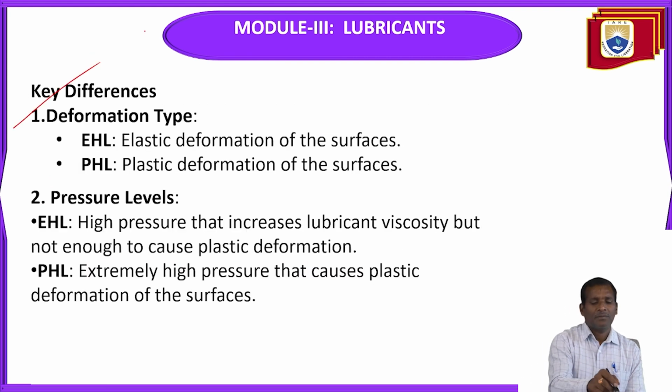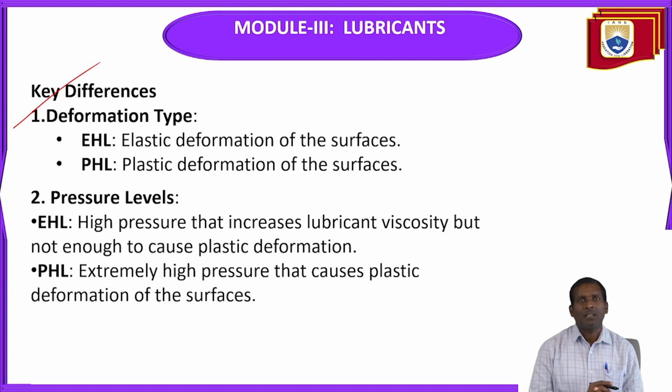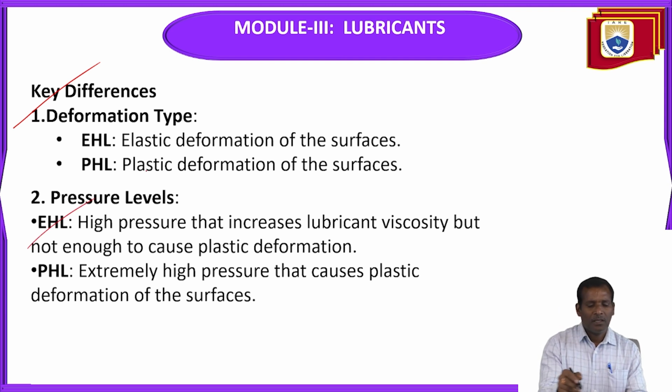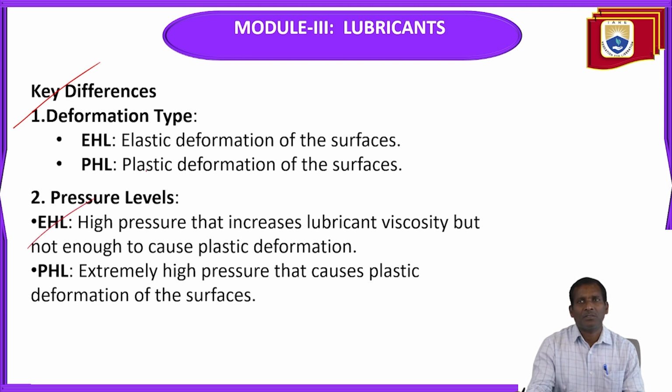Key differences, the major differences between elasto-hydrodynamic lubrication and plasto-hydrodynamic lubrication, EHL and PHL. The pressure levels: in EHL, high pressure that increases lubricant viscosity but not enough to cause plastic deformation. The PHL is extremely high pressure that causes plastic deformation of the surfaces.